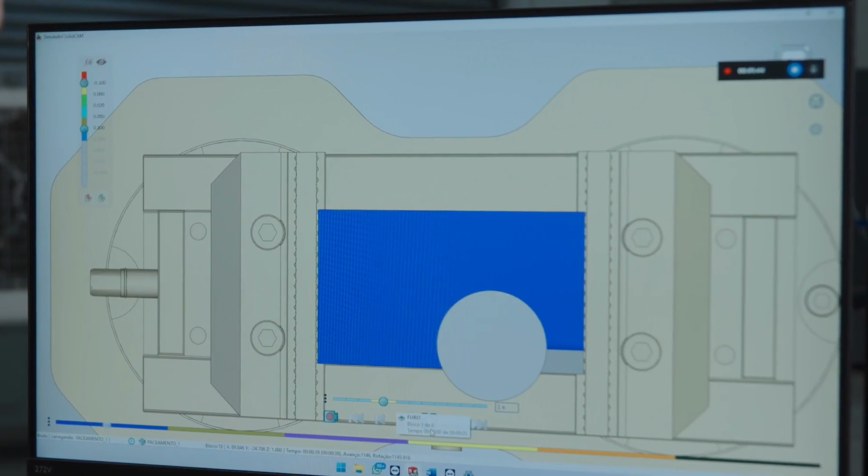of the process. What happens is that when I have less area for material removal, I can keep increasing the feed rate of the tool. What's happening here? I have one area with very little material, two areas with 50% of the tool, and one area with about 40% of the tool. And in all these areas, you are working with the same feed rate, with the same tool speed, whereas I could have different feed rates for different steps. Just in facing alone, that would already save me time.